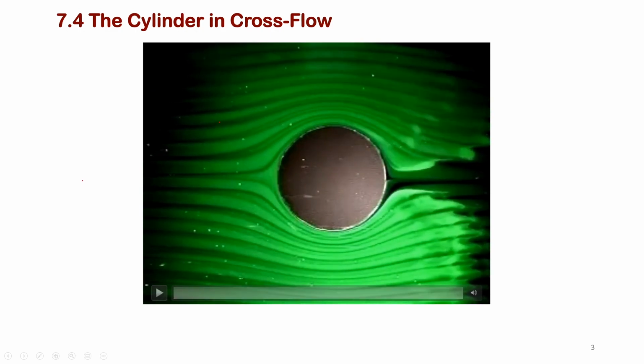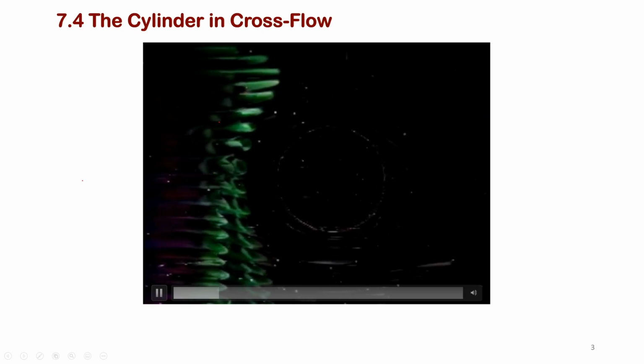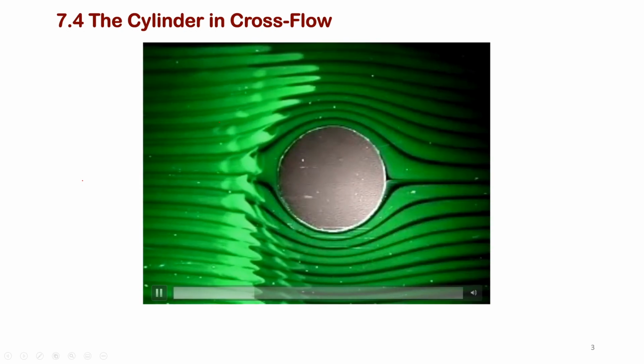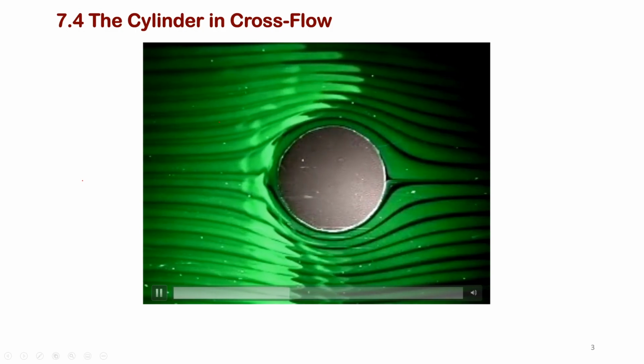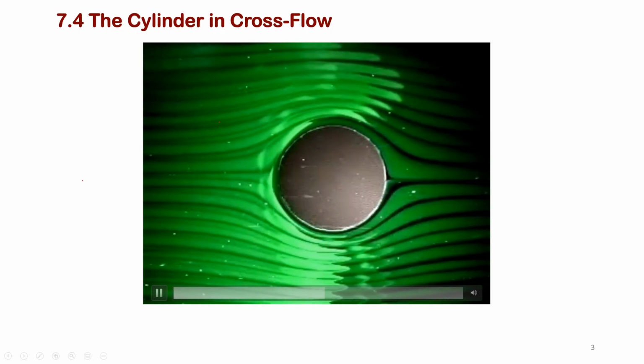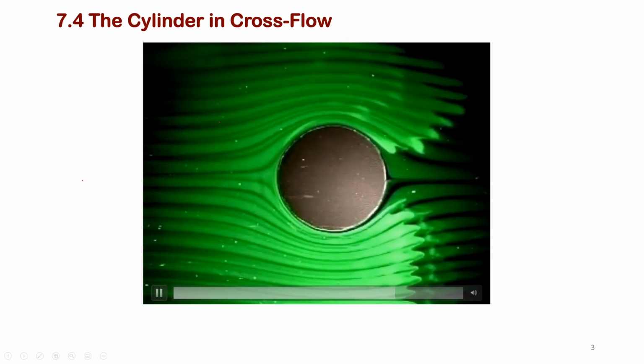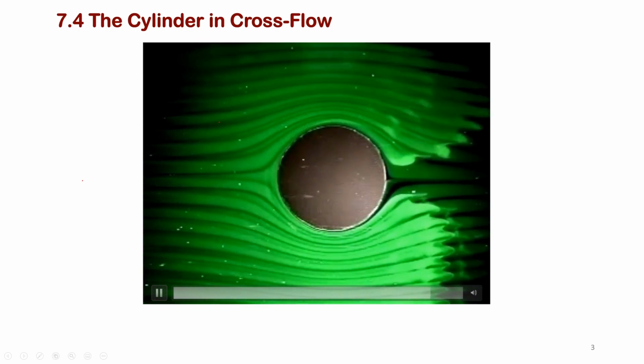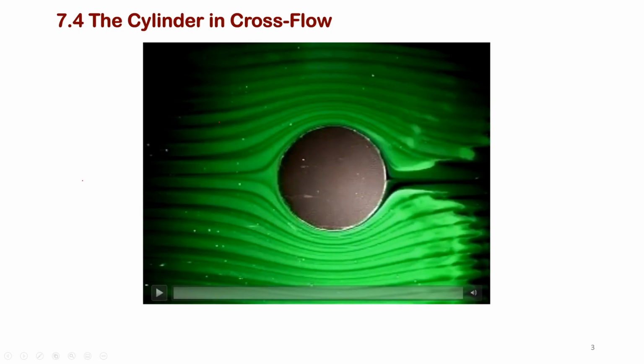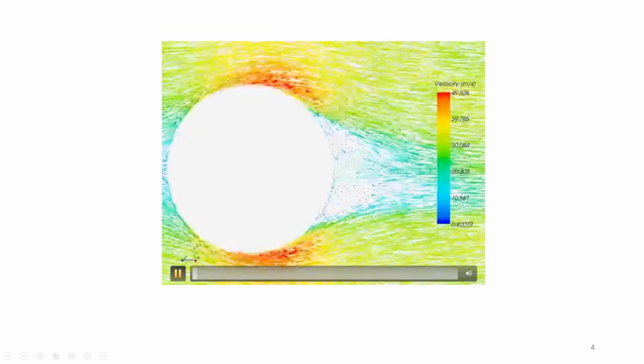I would like you to pay attention to the streamlines around the cylinder, in particular very next to it. I want you to understand at what point the fluid is grabbing this cylinder and at what point the fluid layer is detaching from, or separating from, the cylinder. So that is one observation. This is another video.